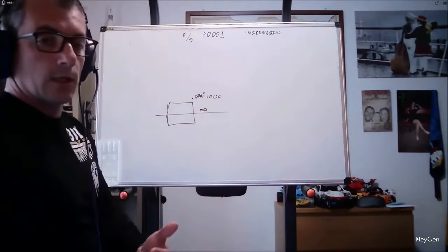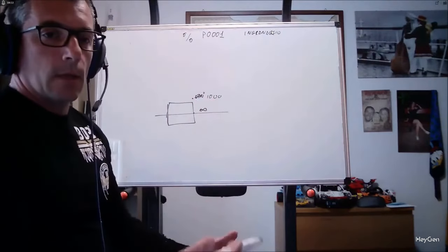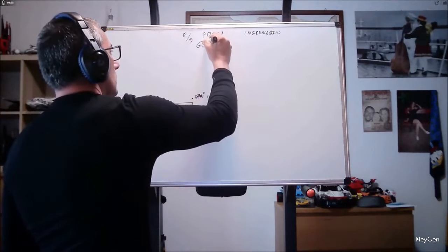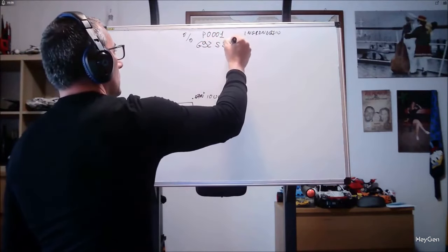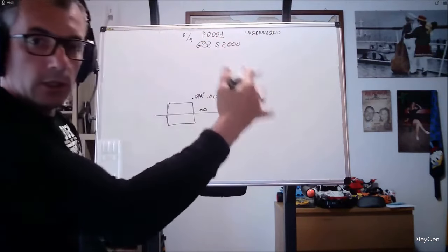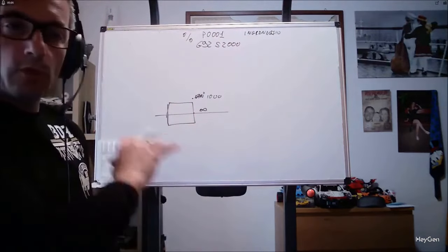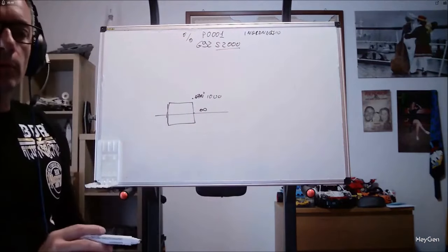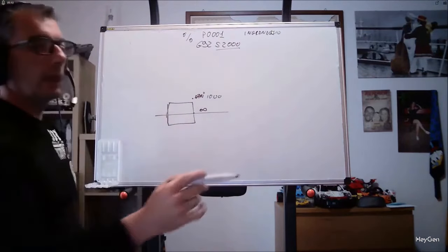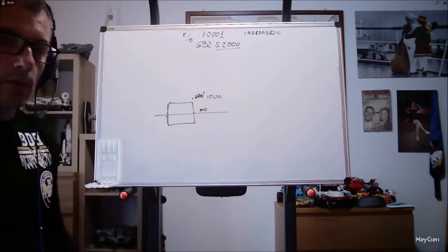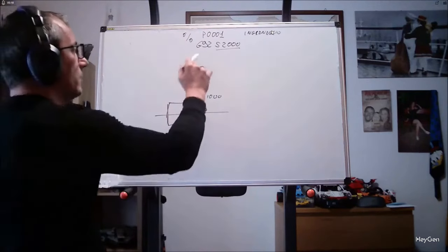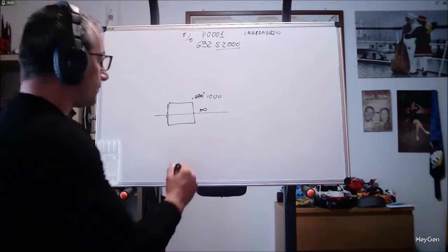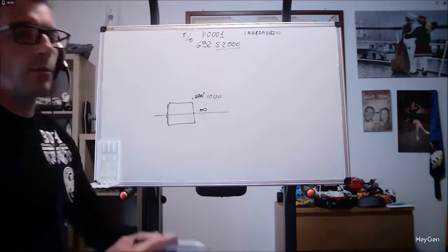So normally, depending on the type of machine and the weight of the piece and some variables related to the grip, it is a G92, S2000, 3000, 4000, 5000. That is, we tell the machine that at any moment during processing, you can never exceed these RPMs. G92 is repeatable within the program, meaning if we perform multiple operations and want to change the maximum RPM for safety reasons, we can do so. So if we have a piece weighing 80 kilos, we can do it.